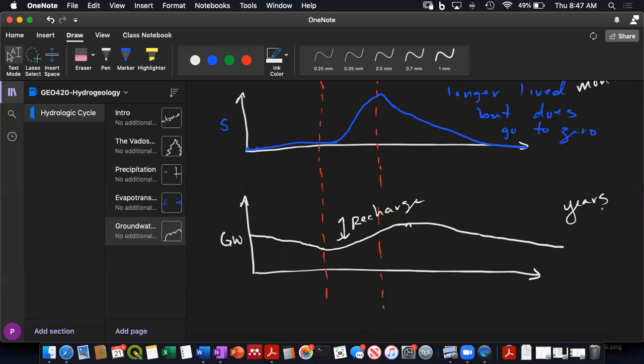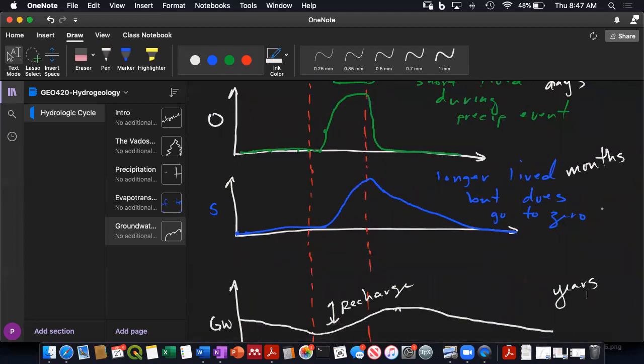Now, I'll just say there's a whole branch of hydrology that's essentially devoted to trying to pull out the signal of these three different processes. We do that both through the discharge alone, and also through the chemistry of that discharge. You could imagine that rainfall has a different amount of chemicals in it than water that's been underground for a long time. So we can measure not only the discharge in the stream, but the chemistry of that discharge and try and back out these different components. We're not going to try and do full hydrograph separation in this class because we're focused on the groundwater. What we're going to do is focus on what happens to the base flow, and whether we can use that change in base flow to estimate the amount of recharge to our groundwater system.